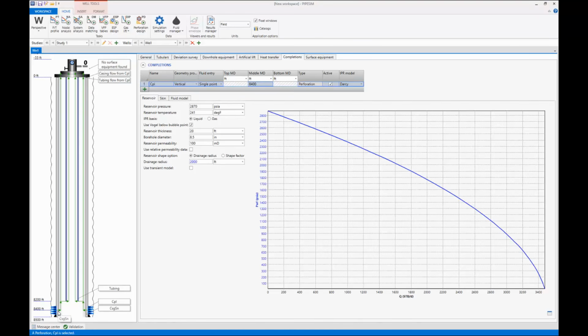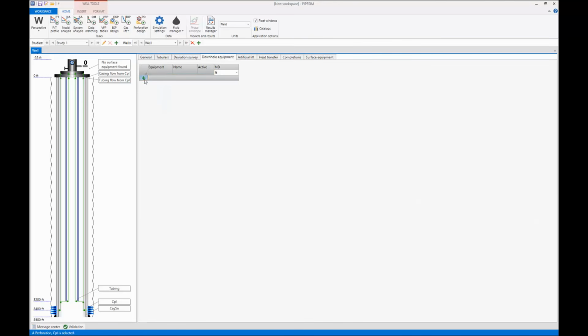Look at the well schematic. We can see a dual flow path represented by green lines with arrows. Based on the current well schematic, the reservoir will produce concurrently through the annulus and the tubing. To isolate the fluid flow to a singular path through the tubing, we add a packer at 8,150 feet. This completes the process of building the well model. Now the nodal analysis simulation task can be run to determine the well deliverability.